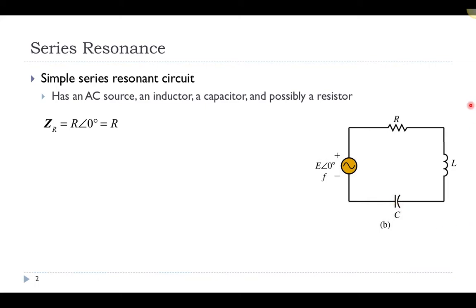So even in a circuit like this, there is a natural frequency of vibration, and if we can match that natural frequency, we can actually get the maximum amount of power out of that circuit. And specifically, of course, real power. So at resonance, we get the maximum amount of power through that particular resistor. And so that's what we're going to focus on.